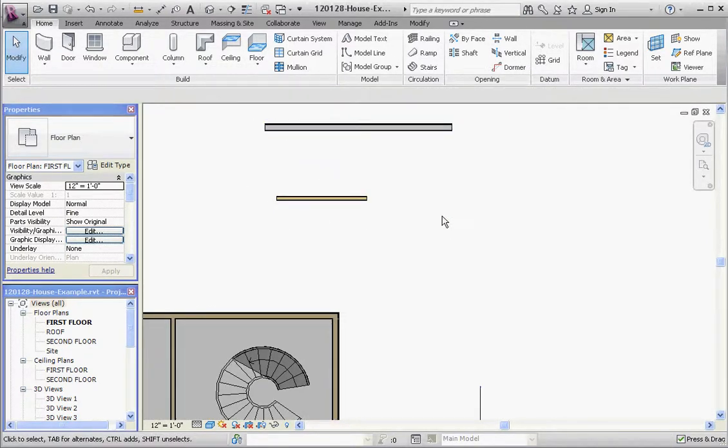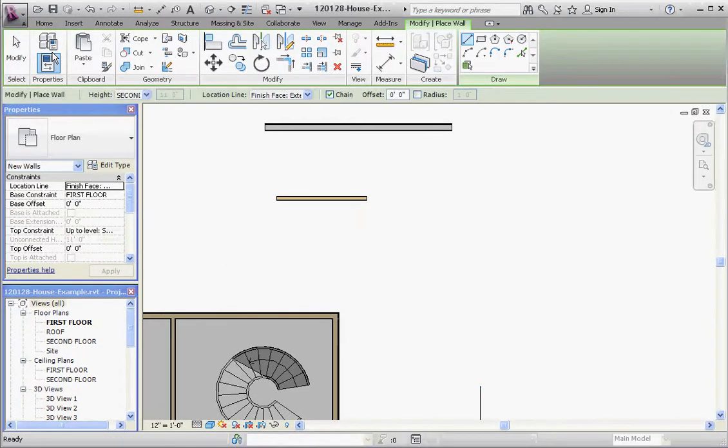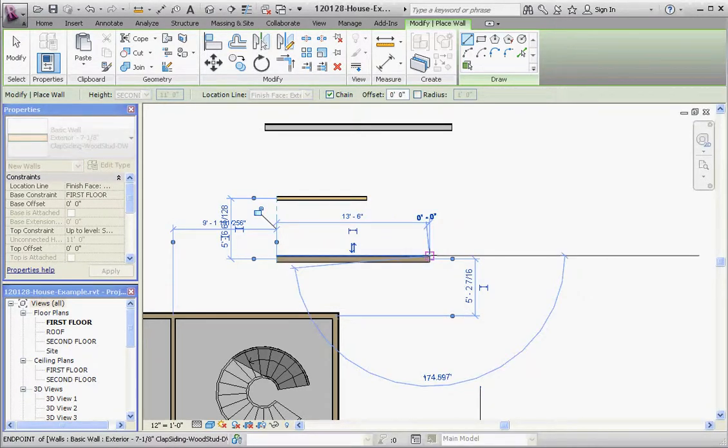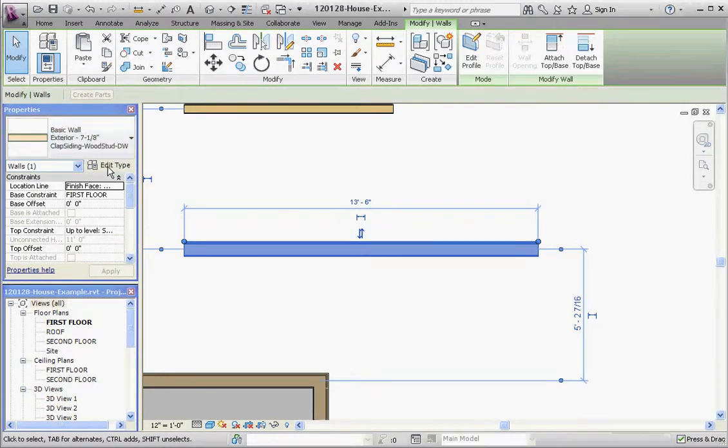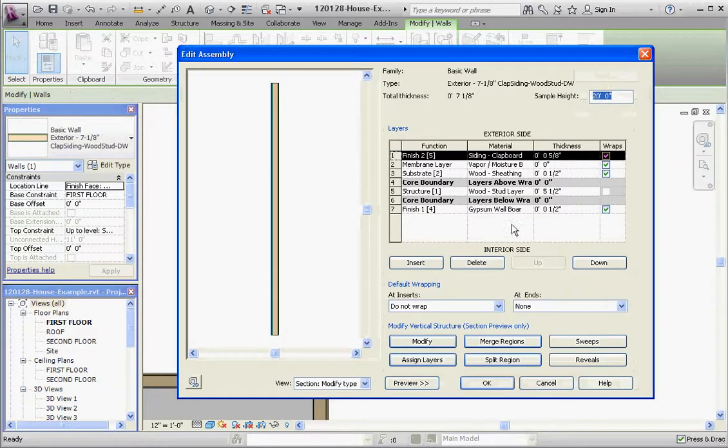The third wall is going to be your wall of your own choosing, and here are the constraints for that. You need to create a wall with 5 different layers. It needs to have a vapor, insulation, or an air barrier layer in there. So let me go ahead and insert a wall that I had created myself. That's our 7 1/8 inch wall that we created in AutoCAD. Yours has to be a little bit different than that. But because you're familiar with the 7 1/8 inch wall, let me go ahead and edit that wall and show you what's inside there and show you what you need to do to that wall in order to make your wall unique, but with the requirements of what's required here.